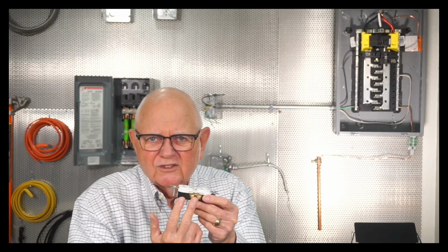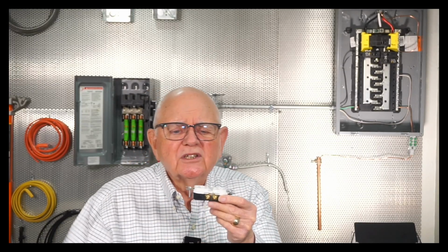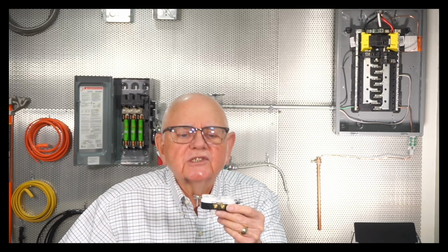Now, I mentioned the multiwire branch circuit where we break that tab on the hot side, and we have two separate conductors coming in, one to each half of that duplex, and I have a voltage between those two conductors. Now, some of the requirements in 210.4 for our multi-wire branch circuits is, first of all, they have to originate from the same enclosure. Okay, that makes sense, doesn't it?